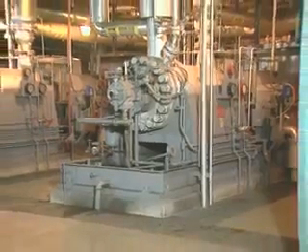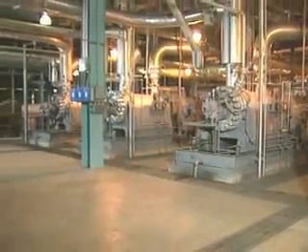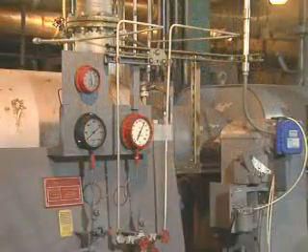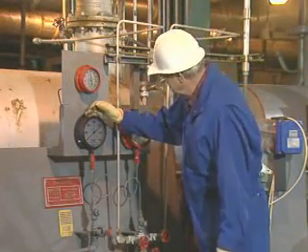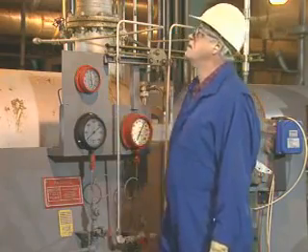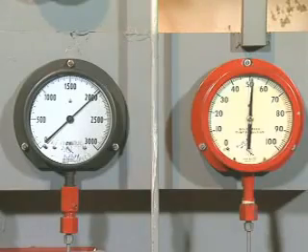A typical condensate and feed water system includes several multi-stage centrifugal pumps. Checking the pressures, temperatures, and lubrication for the pumps during normal operation of the system is a routine operator responsibility. Checking pump suction and discharge pressures periodically helps ensure that each pump is operating correctly and that proper flow through